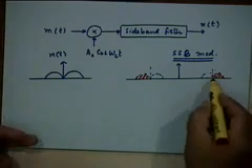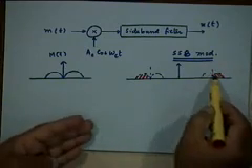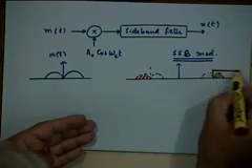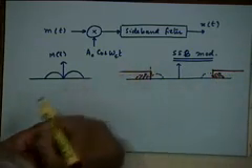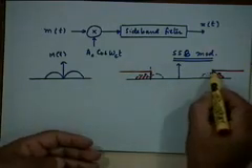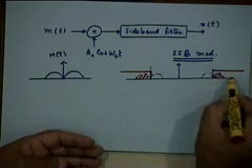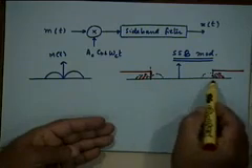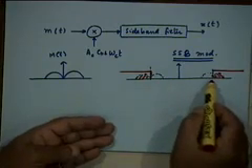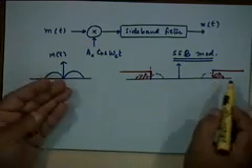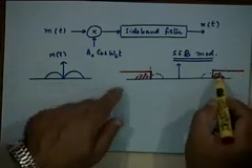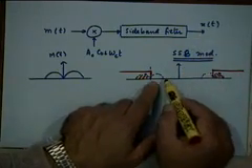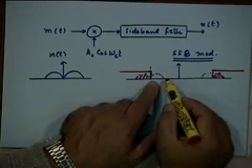A high pass filter can separate the upper sideband from the lower sideband, so you require a filter whose transfer function is 1 for |f| greater than fc and is 0 between minus fc and plus fc. For |f| greater than fc the transfer function is 1, so it will pass this spectrum to the output, and the other spectrum will get attenuated, eliminated.